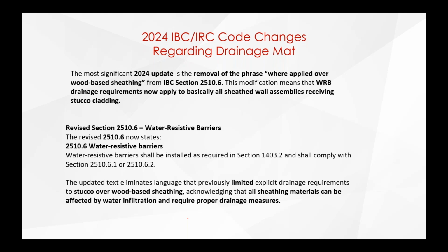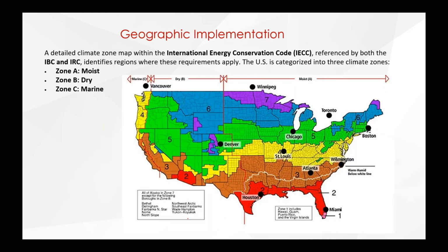The main thing about this text is it took out "over wood-based sheathing." Those that know the code out there, you know it was only applying to stucco going over wood-based sheathing, but now that's been taken out. So that's a big change.